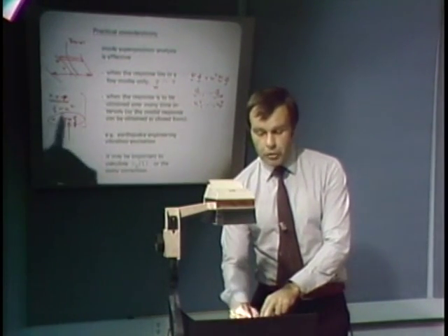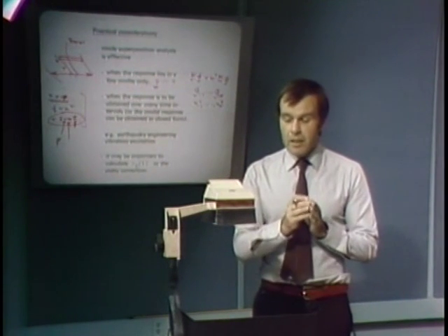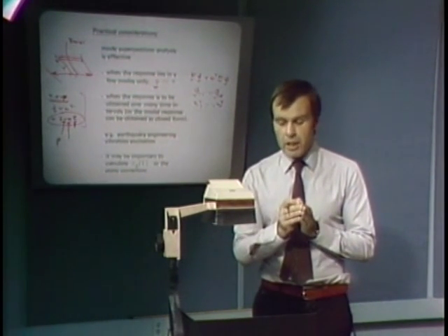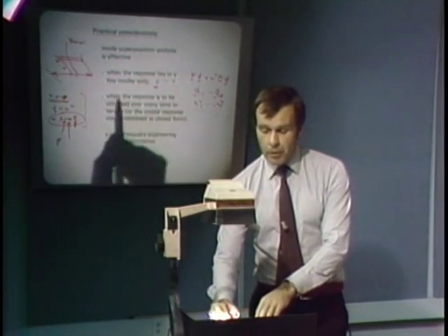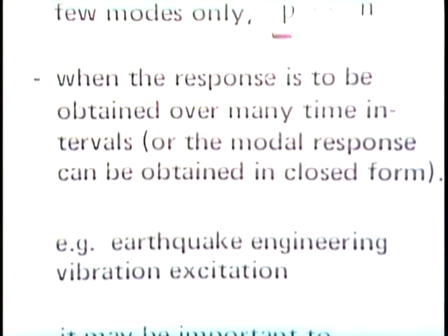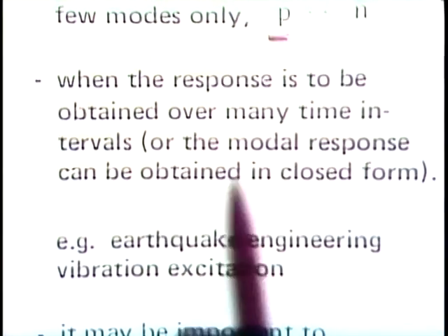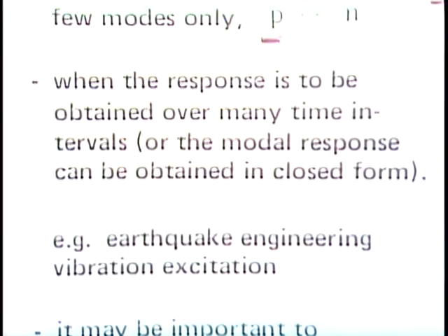Of course, this is an approximate count. So basically, you can see that in the solution using mode superposition analysis, the number of operations in the time integration of the decoupled equations is relatively small, and in fact, this solution can be obtained very, very effectively. The time integration of the decoupled equations is very effective in an actual practical analysis.